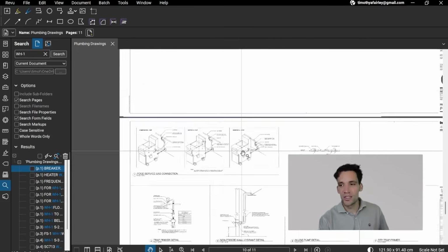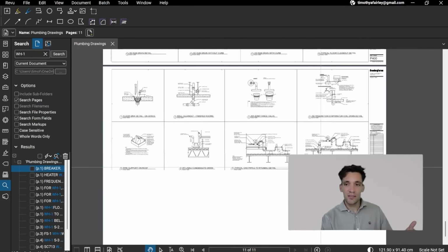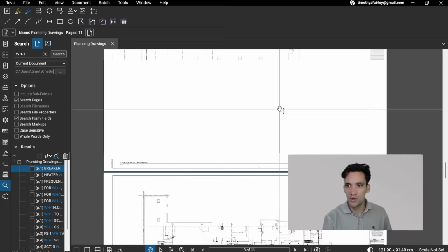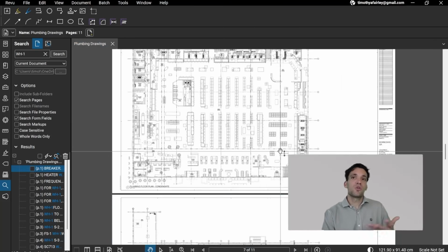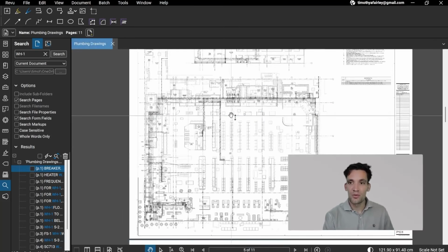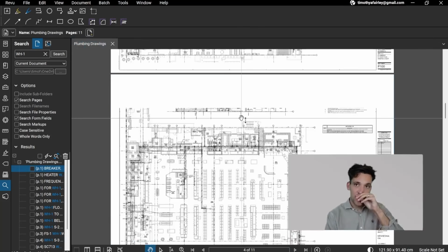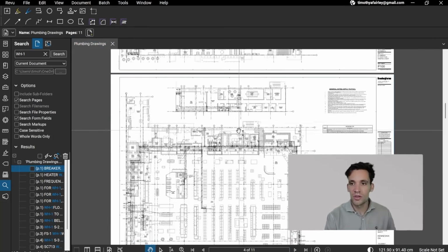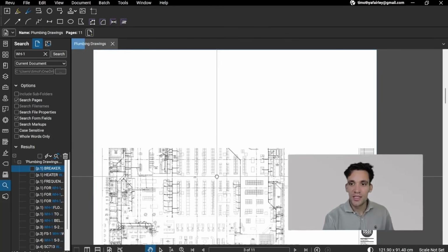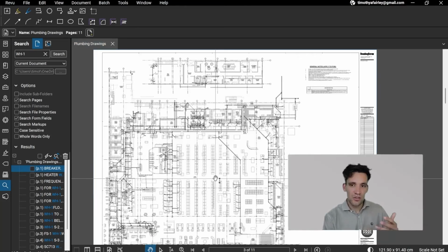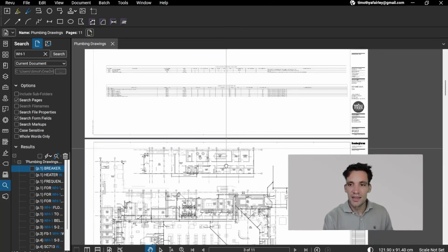Okay, so how are you actually going to use all this information and basically turn this into a full bill of quantities? Well, number one, you need to work out what you need to measure. So for us, this is going to be for the different trades. So cold water, hot water, plumbing, we're going to need both the counts of all the fixtures, fittings, and units that we're installing, and we're going to need the lineal meters of that.